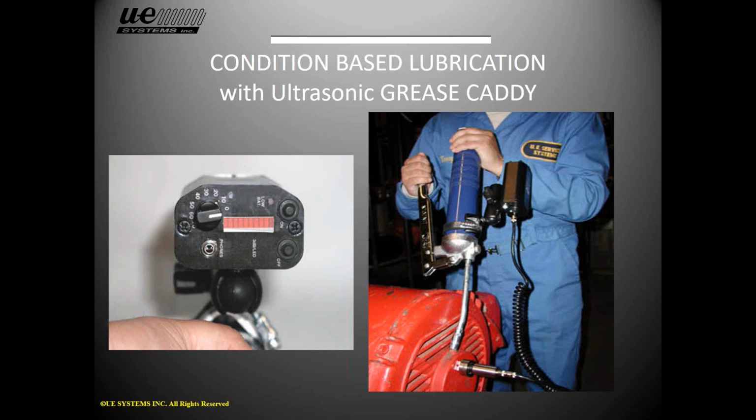Now, I remember I bought this first tool in 1999 at the facility I was at, and within 4 months, we'd cut our grease consumption back by 30%. We were actually over greasing everything. We were greasing on a time basis, and a lot of times we found out the bearing didn't actually need any grease after that week cycle or month cycle. So again, a 30% reduction in grease in just 4 months. And we were using it to determine frequencies and volumes.